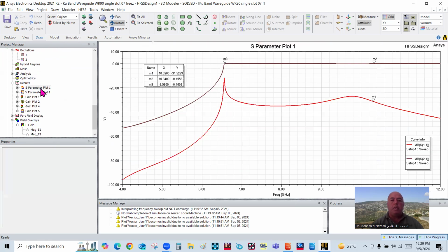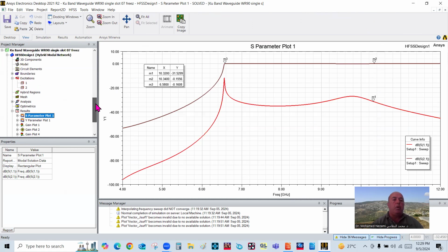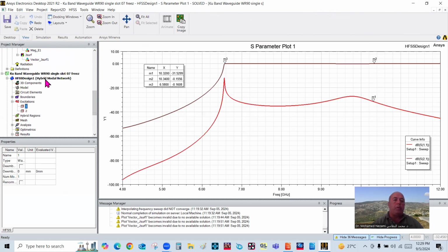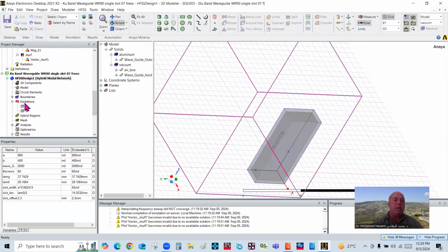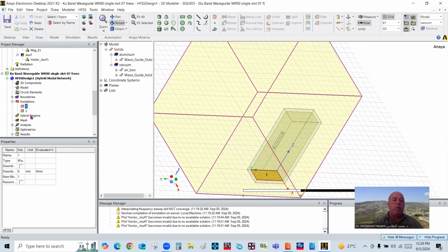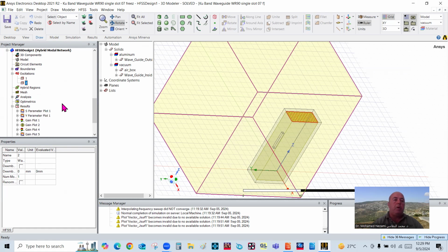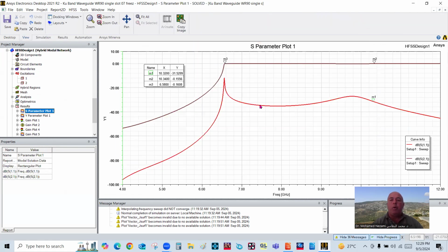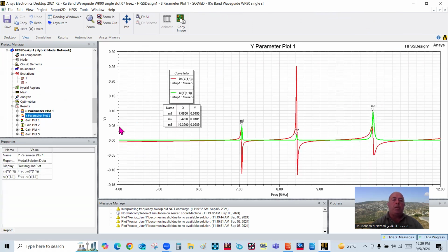And for this one, when I monitored, of course, now it's not really an antenna, but a structure with two ports. You can see that I'm putting a wave port in here, and then I'm putting another port on the other side, and I'm monitoring. What I do is monitor the transmission and the return loss, and everything is fine.